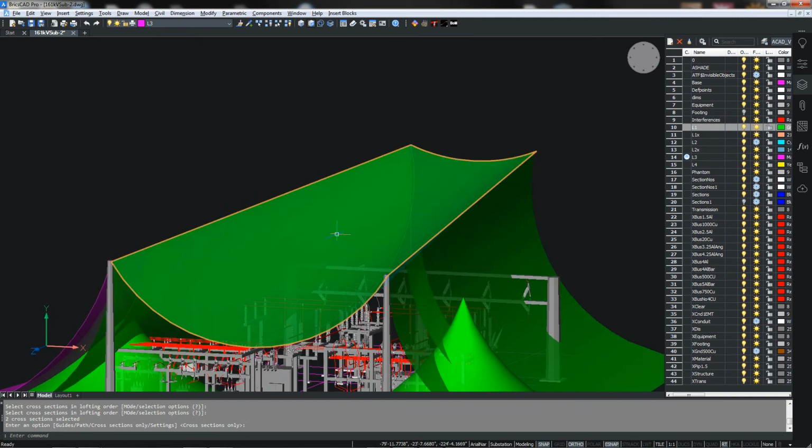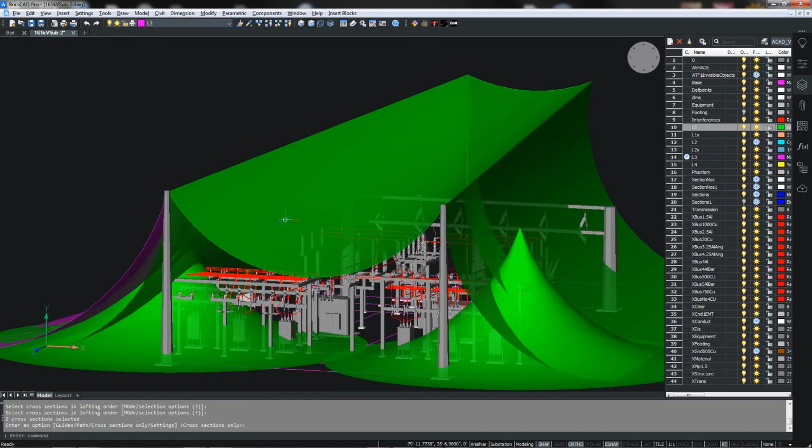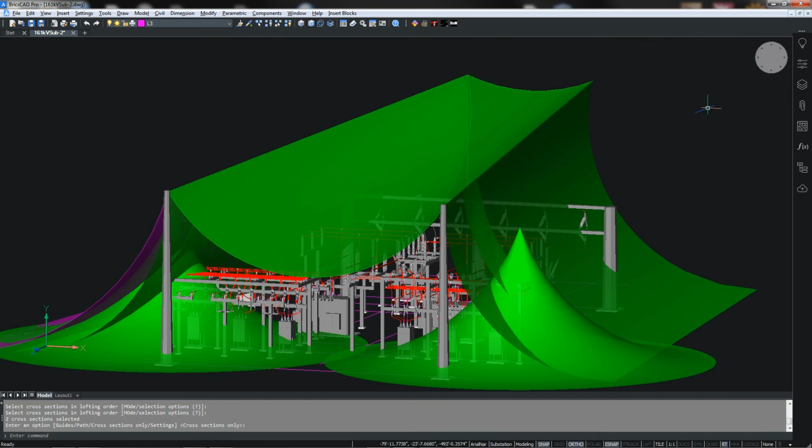As a matter of fact, what we used here was what I might term the lofting arc model, where we've used the equations from the rolling sphere to develop the radius of the sphere, and then used arcs to represent the contact points of our sphere, and then generated surfaces between those arcs to see what our coverage is. And so with that, that's going to end this demo.